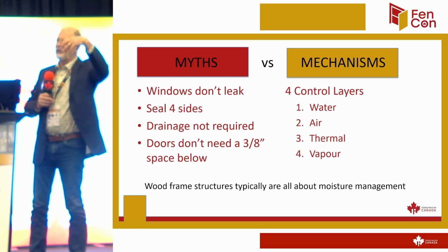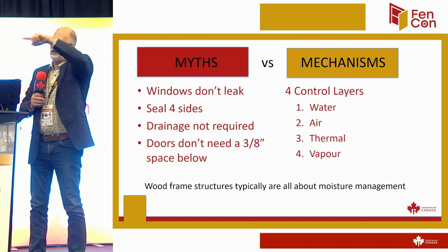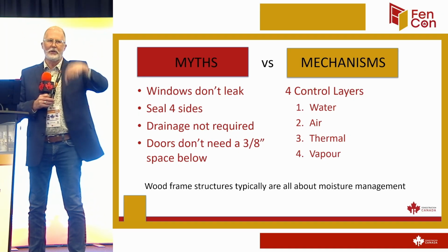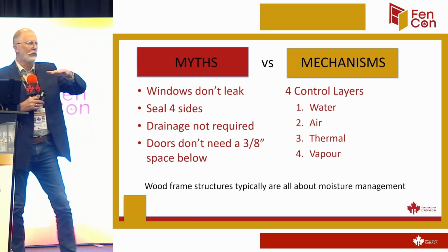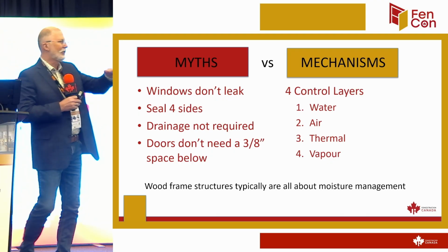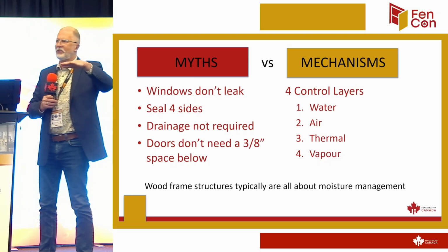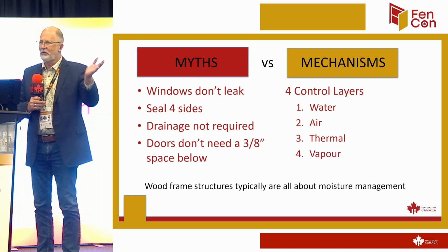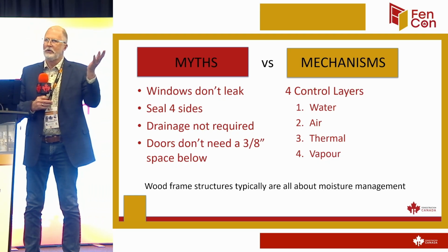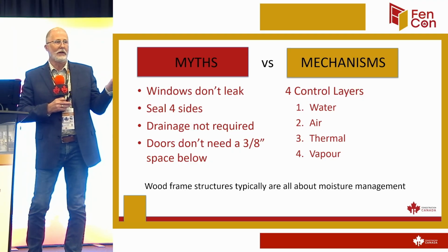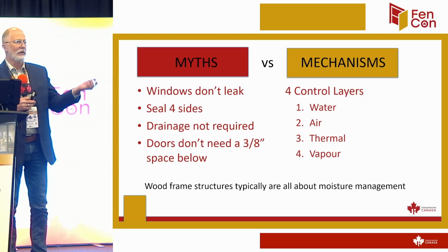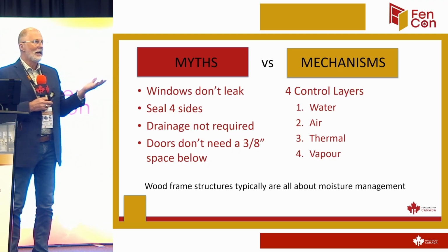Well, that tells us that the water gets in that window, it runs around the rough opening, and it sits on the bottom on a horizontal surface. And what do we learn about tar paper on a horizontal surface? A 30-minute tar paper is good for 30 minutes, a 60 is good for 60. A house wrap, what about the corners? So we just don't have the protection there. Anybody that's renovated knows what the window looks like when you pull that out and the damage that's occurring.